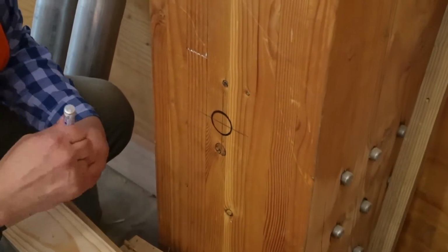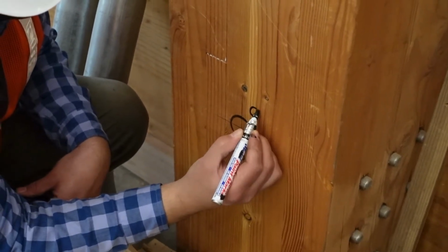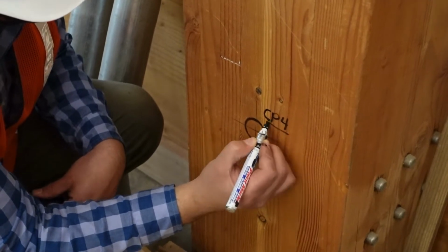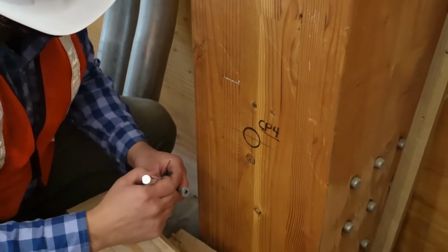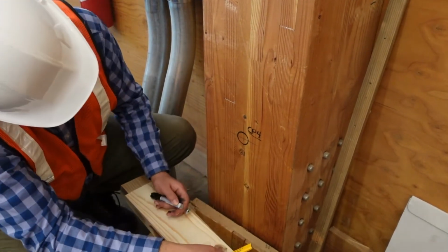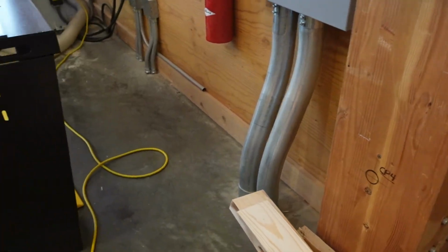Another important part of the process is to have target points distributed around and inside the specimen building. When the post-processing is being done, we will have these constraint points that will join the cloud points from different scans. For this, we use sticker paper with black and white colors that can be detected later by the algorithm.